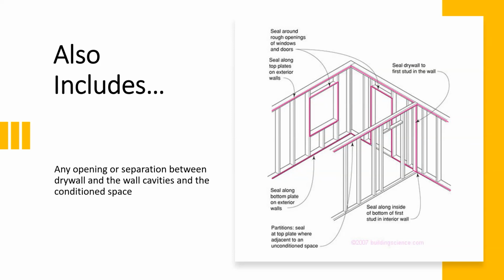As we see on the right-hand side, some people say it's extreme. In my opinion, it's what should be done on all houses. You see a gasket, either a caulking gasket, a poly gasket, or a foam gasket being rolled out and stapled on all of these areas: around window openings, around door openings, around the base plates, around the top plates, all of it, and even at the T-wall intersections. It needs to have all of this done. It needs to have all those sealed.